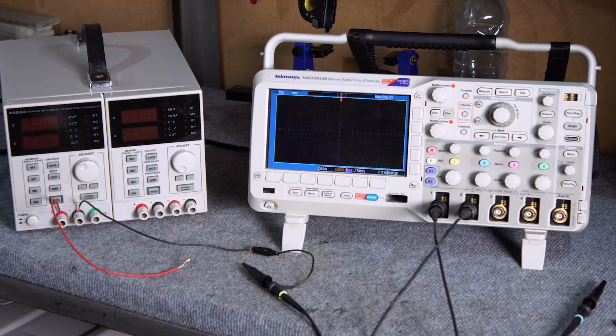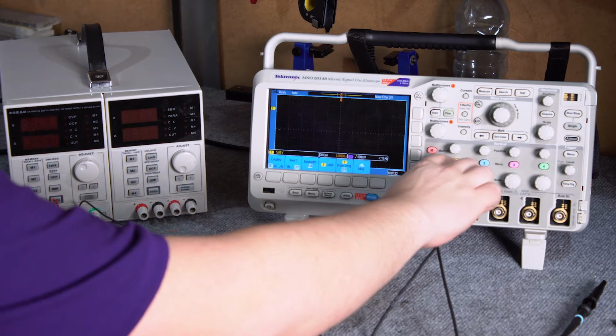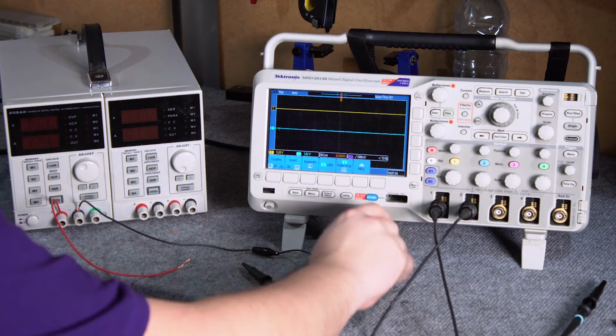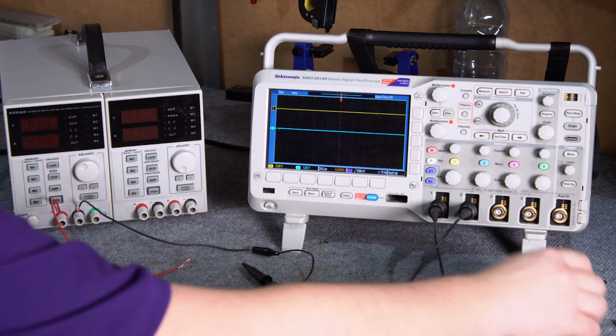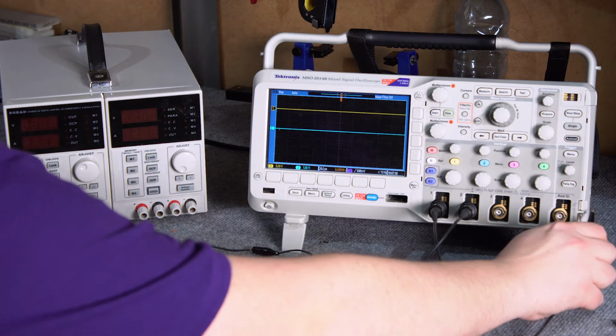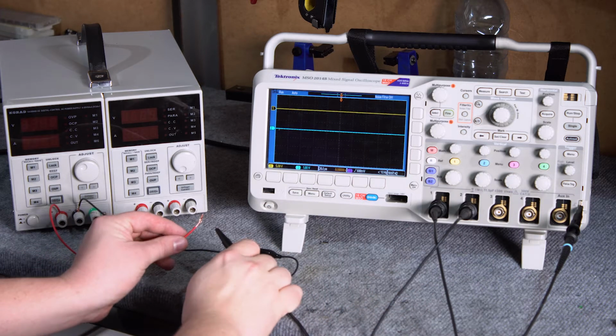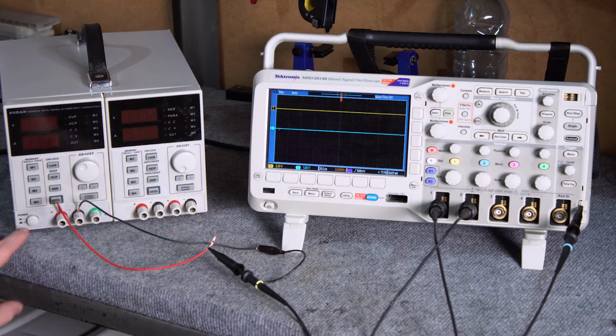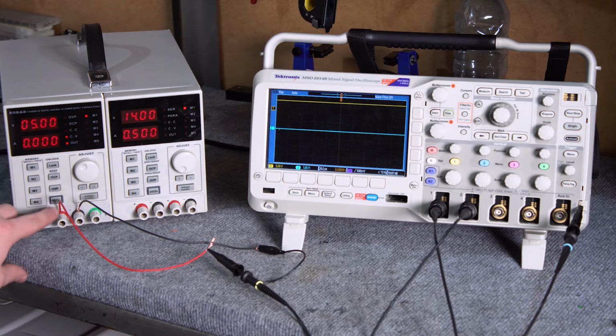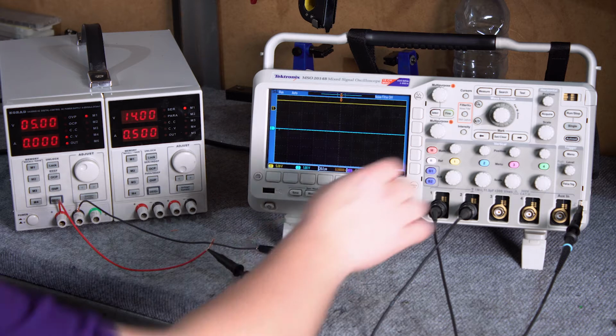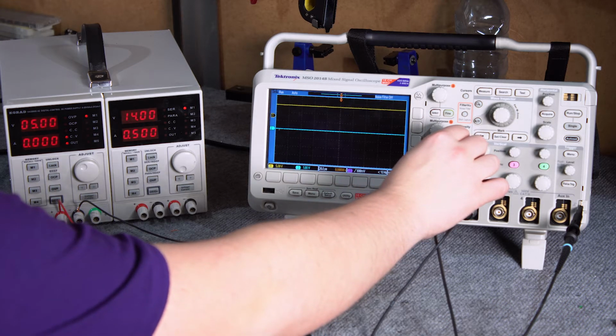There are usually 3. The first is GND. The input is switched directly to the zero of the oscilloscope, so we can then calibrate the position of the waveform on the screen. The second is DC. Then the voltage from the input is drawn on the display without transformation, of course taking into account the selected range. The third type is AC. Here the capacitor in series cuts the fixed signal components.